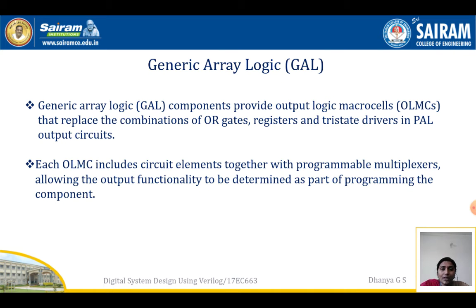Now we'll move on to the generic array logic, which is called GAL. These components provide output logic macro cells, which we'll call OLMC, that replace the combination of OR gates, registers and tri-state drivers in PAL output circuits. In the PAL output circuit, you have seen all those things. They can be replaced by OLMC.